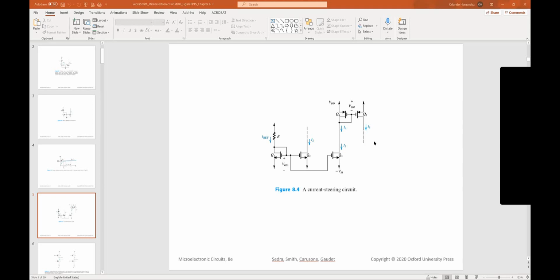In fact, there is a very popular digital to analog conversion architecture called current steering DACs, that uses powers of 2 as the ratios of the different current mirrors to convert digital bits, which are at either 0 or the supply, into specific currents. When you drive a load and convert to a voltage through a current to voltage amplifier, you get an analog voltage.